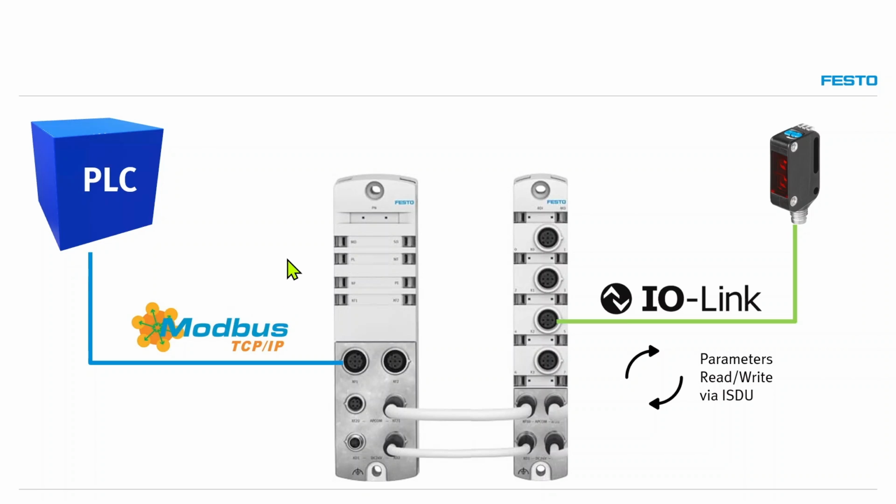So this is the overall topology that I have here. You can have a PLC, as long as the PLC has Modbus TCP/IP communication capabilities, you should be okay. Then we're connected to this CPX-AP-EP module, the EtherNet/IP module that can also do Modbus TCP. The current topology has these four IO-Link master modules connected to it. That's what I'm trying to depict with this image here.